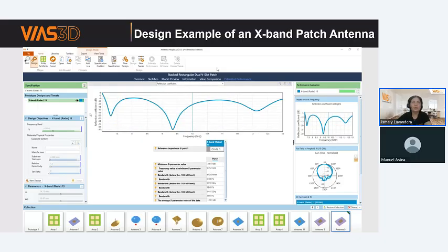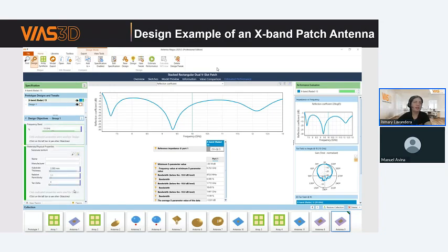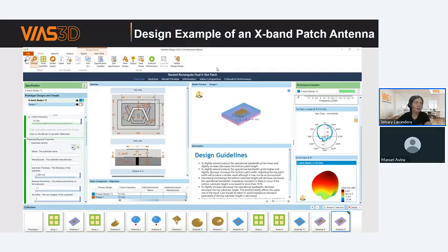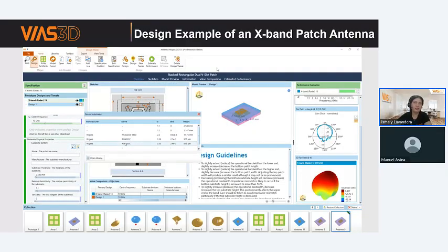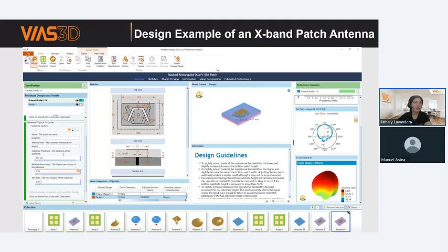But let us create a new design to improve my parameters, to improve my variables. So in this design, I want to add a real material, a physical real material that is commercial. For example, I will go to Rogers, but if you can see, the substrate is telling me that the relative permittivity should be below this value. So it will give me recommendations.